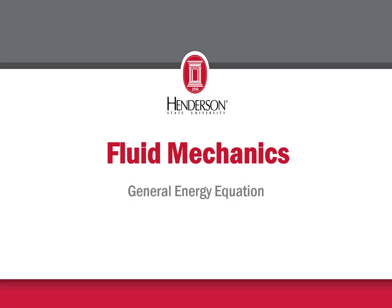In this section, we're going to expand our application of the working energy methods beyond the traditional Bernoulli equation. We're going to include the effects of heat and viscous fluid flow, along with work input from a pump and work output due to a turbine. We're going to restrict ourselves to incompressible flows.